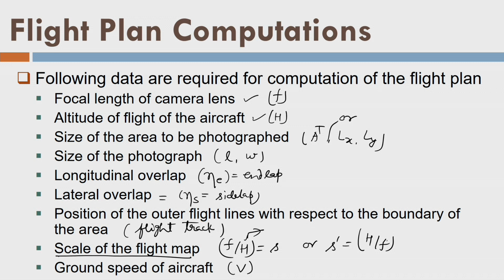This is the flight planning computations. That means I want to acquire the data in the field. Before that, I do some exercise where I know which camera I am going to use. The moment I fix the camera, I know what should be my flight height or the flying height for the given scale, or the scale to be achieved in mapping or aerial photographic mapping.